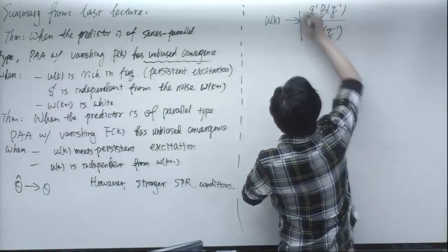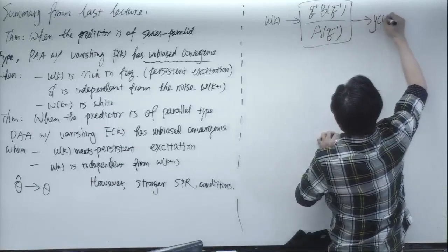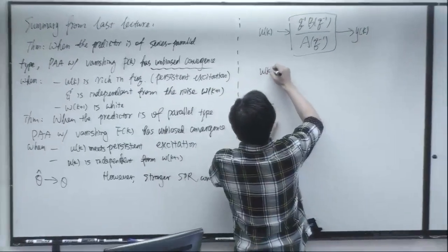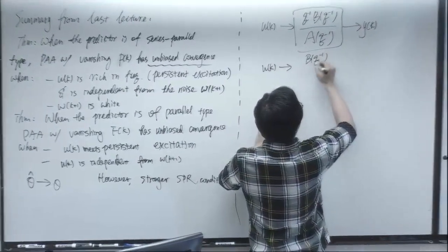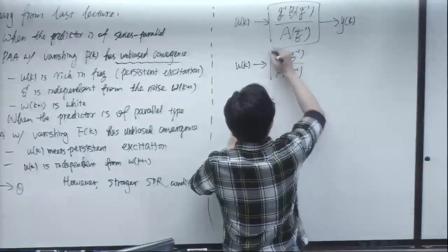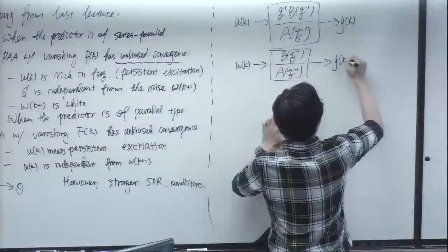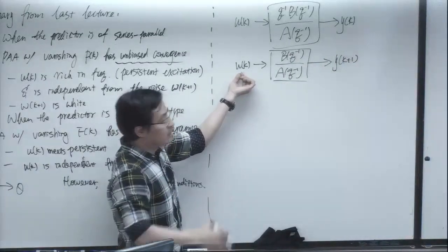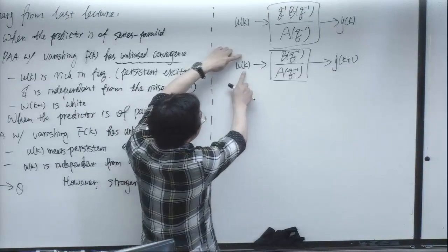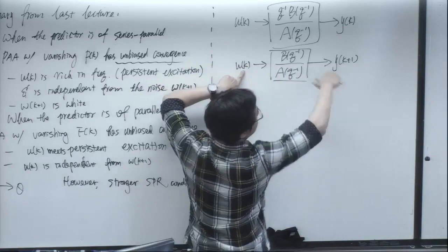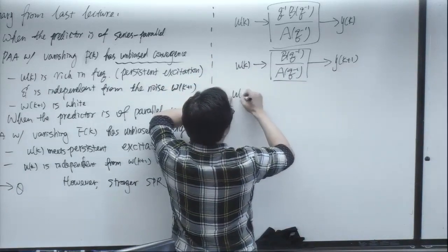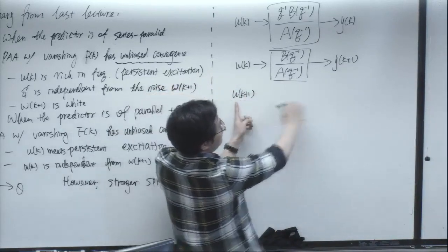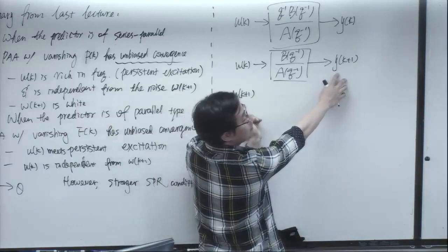Another thing that's relevant from past lectures is this concept where we said a practical mechanical system usually will have, the plant will have a one-step delay inside, and equivalently your control input actually doesn't impact your current output. Think about it this way, because some of you had questions. Your control input UK plus 1 doesn't directly impact your YK plus 1 output, all right?